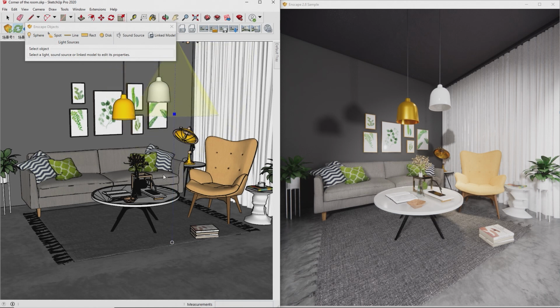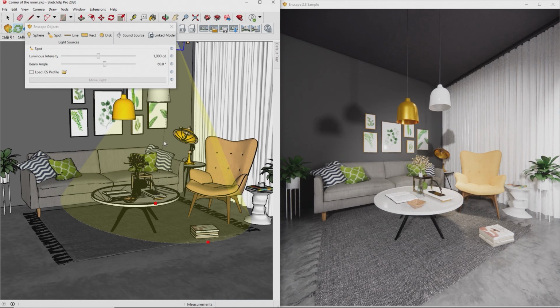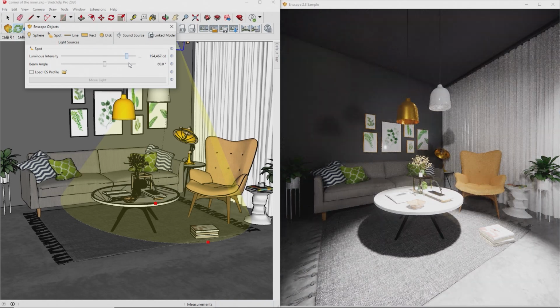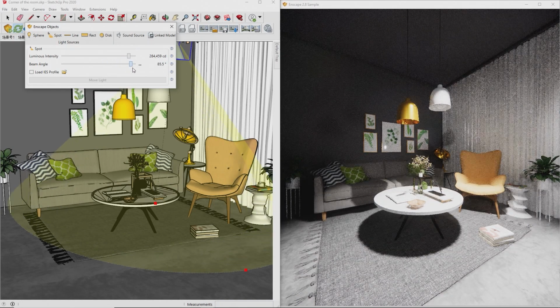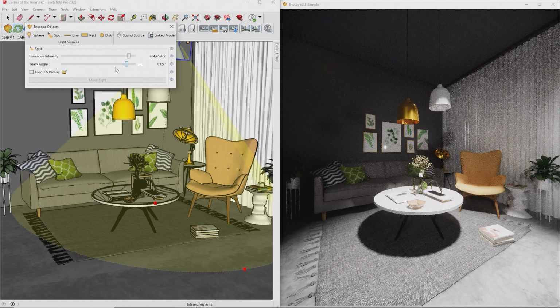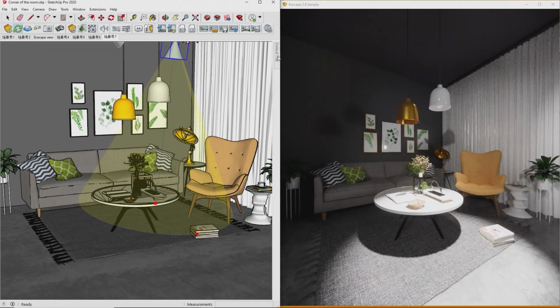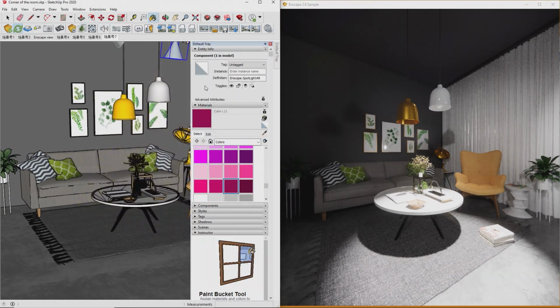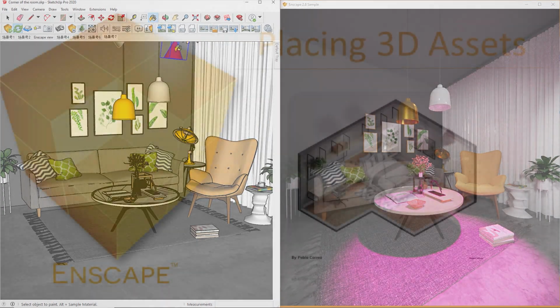The second click will place the actual light source. Click a third time to select a surface to base the placement of the light target off. The last click will place the light target. You can now change the brightness or the beam angle, or use an IES light to increase the visual appeal of the light. You can also color it, simply by painting it using a SketchUp material with the color of your choice.